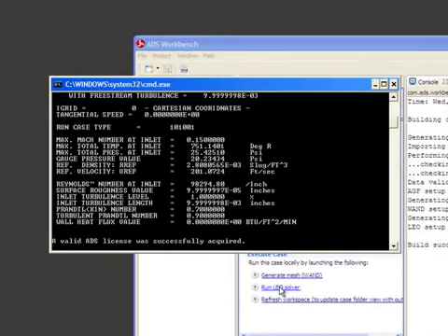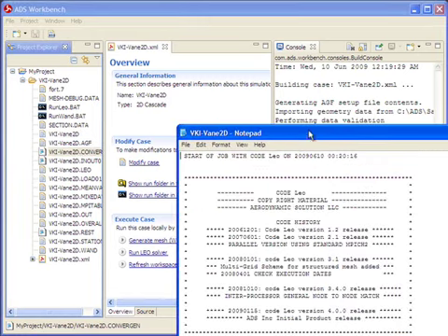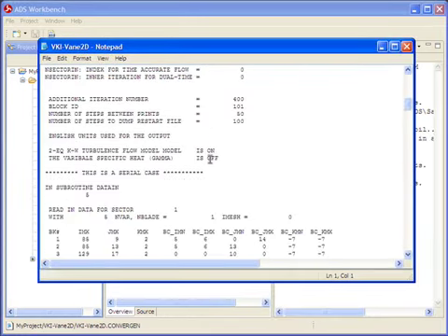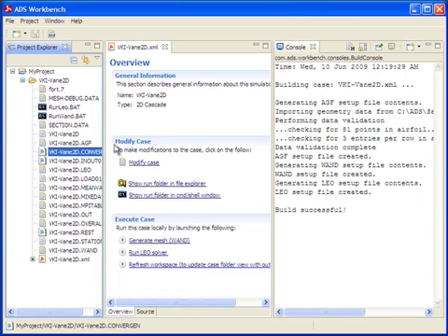So we run Leo, and this will initiate Leo with all the parameters and information that we've provided it. It will allow you to track convergence history on a periodic basis. That can be done so by refreshing the workspace and to look at something called convergence file. If you look at the convergence file, then you can see here that we've actually successfully run 400 iterations in a fairly short period of time here. All right. So in a nutshell, this is the entire cycle from setting up parameters through the execution of a 2D single row steady run.